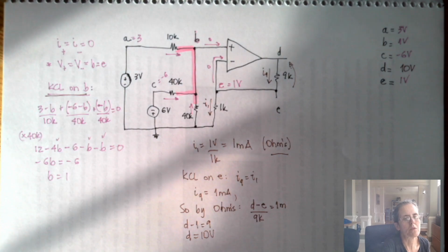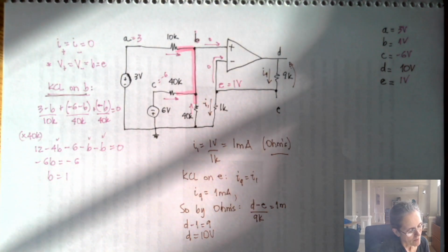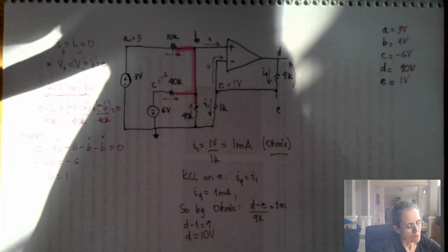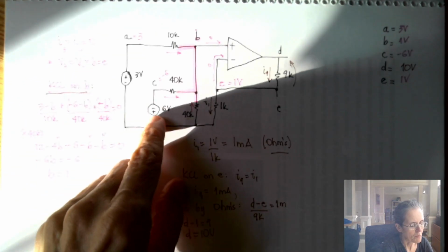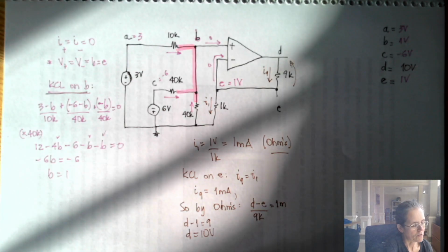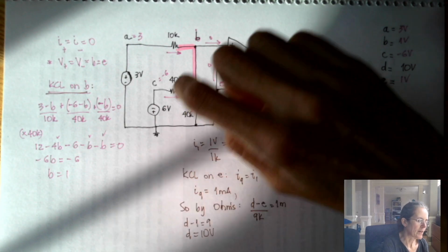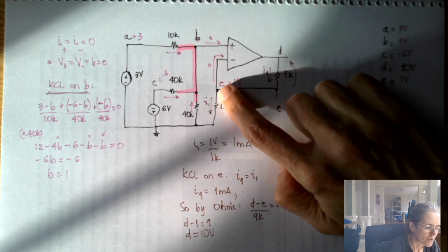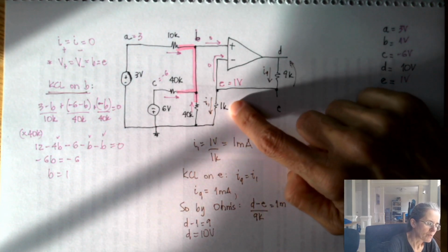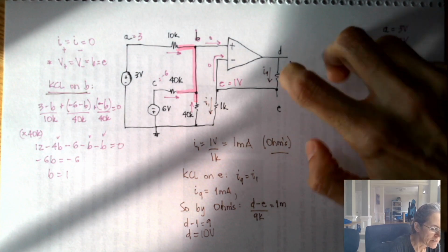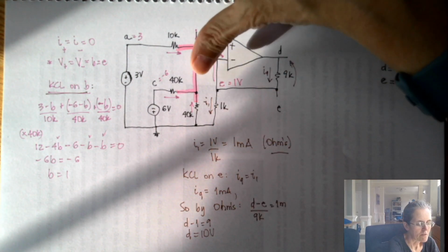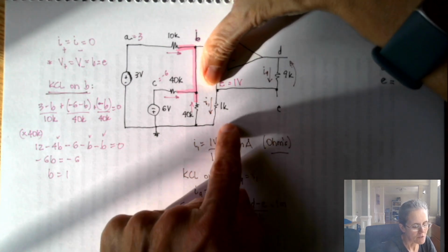I hope this helps. You see that there are several different methods you will be using solving this. Sometimes it's source transformation. I think some people source transformed this and source transformed this. This would have also worked. To find first this voltage, then mirror to E, and then know that this really is a voltage division. So if this is 1 volt, this is 9, you could have used voltage division and said D is 10. Because this current is 0, there's really only these 2 resistors here.